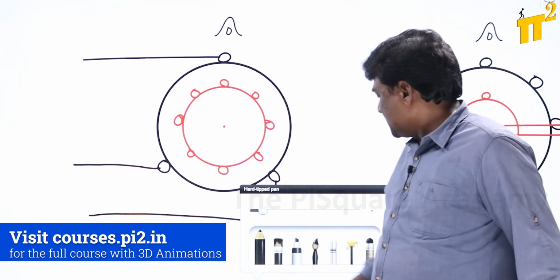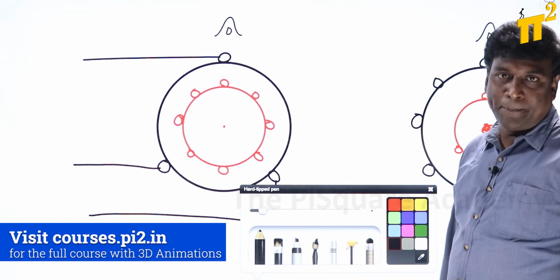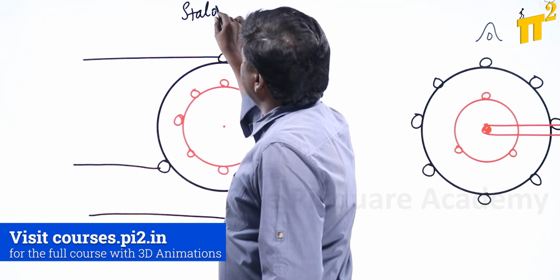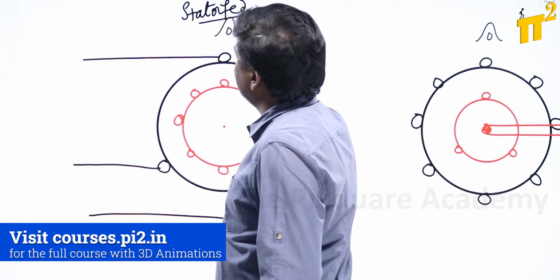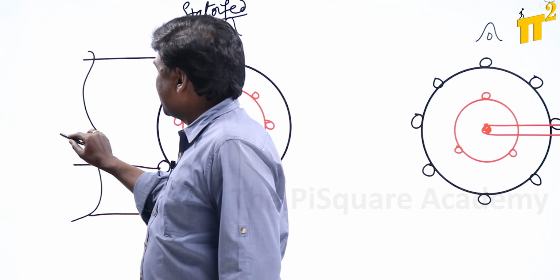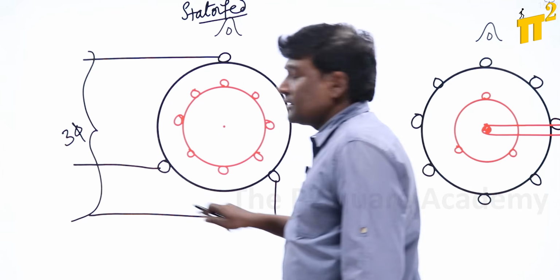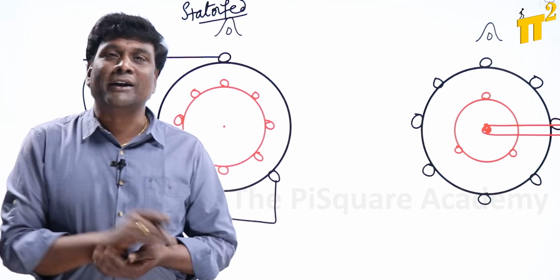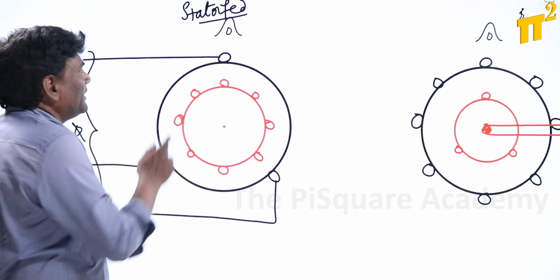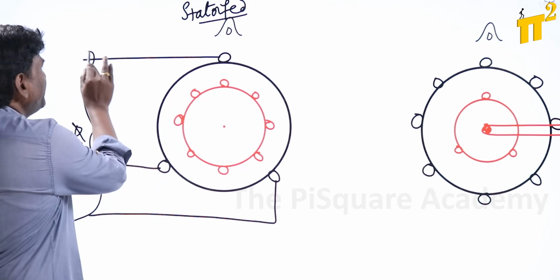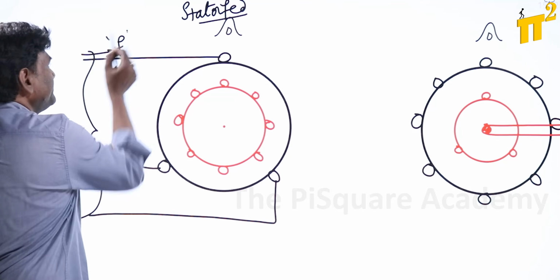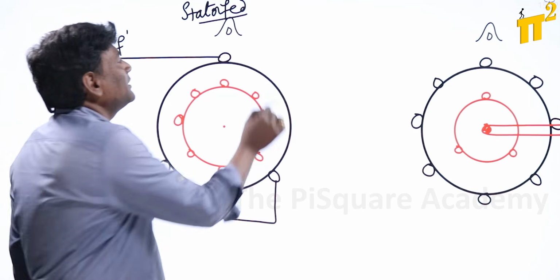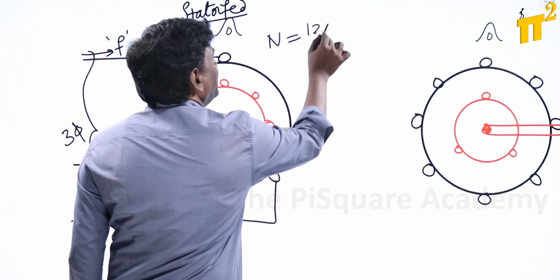Now the next thing is, actually here also multiple times questions came. Okay, now this is stator fed, because we are trying to give a 3-phase supply to the stator. The rotor is going to be short circuited, and I don't want to enter into much analysis. But anyway, the moment it's stator fed, frequencies are going to be constant because we are supplying. So the moment frequencies are constant, Ns is going to be 120 F by P.